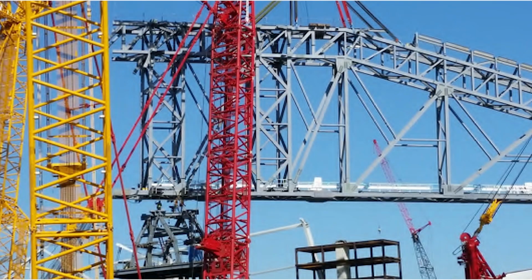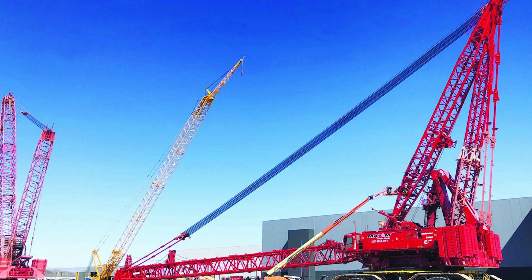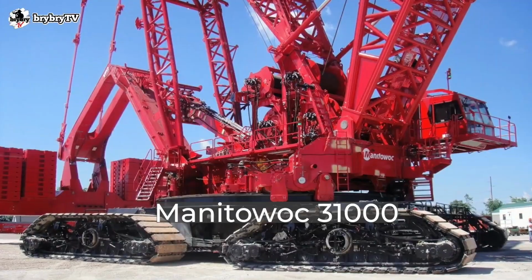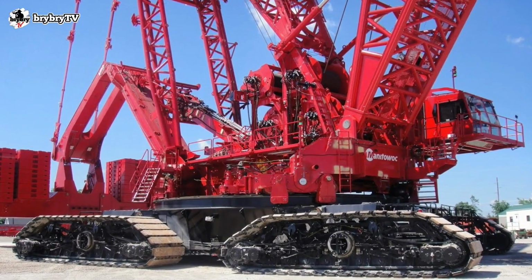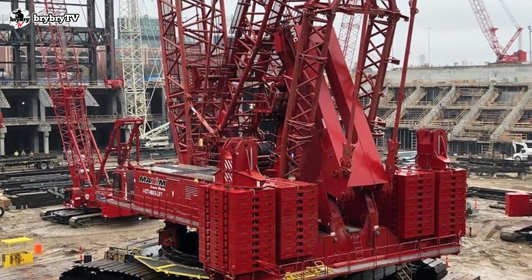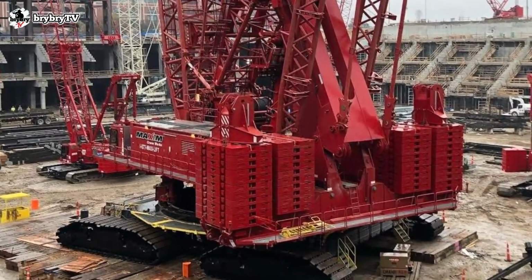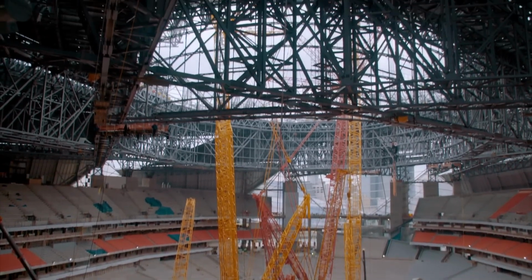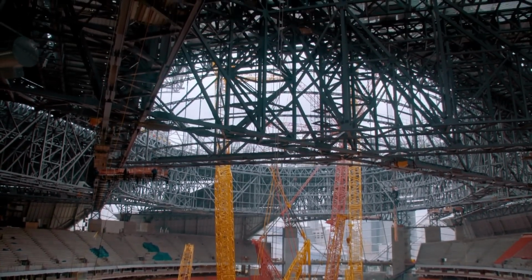During the construction of the megatrusses at the Mercedes-Benz Stadium, various types of cranes were utilized to safely lift and install the massive steel components at great heights. In particular, the Manitowoc 31000, one of the largest cranes in the world, with a maximum lifting capacity of approximately 2,535 tons, served as the primary crane, supported by several auxiliary cranes throughout the erection process.